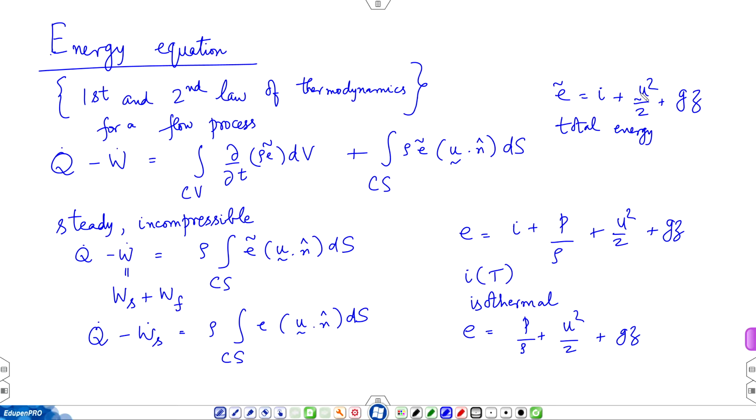Now, in a way, this entire discussion, the presence of internal dissipation, which is also called viscous dissipation, because viscosity is at the root of the conversion of kinetic energy to internal energy of the medium, which is then transferred to the ambient. So, Q dot is not 0, in fact Q dot is less than 0. So, a necessary consequence of the medium being isothermal is that Q dot is less than 0.